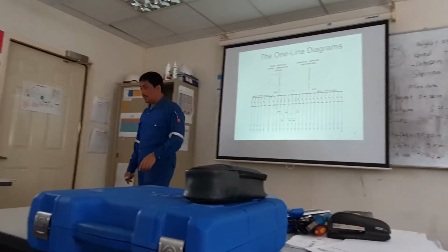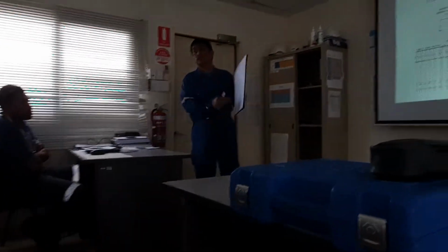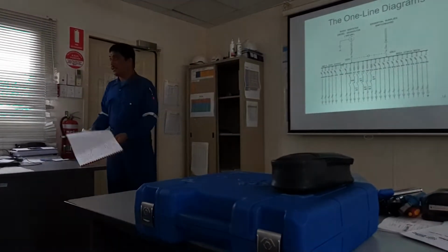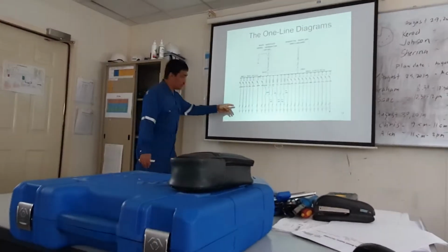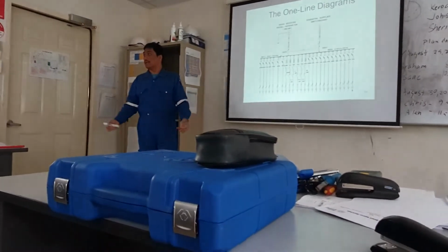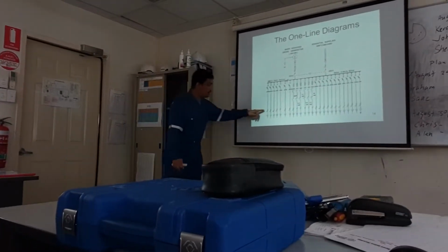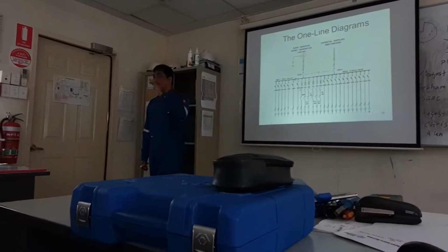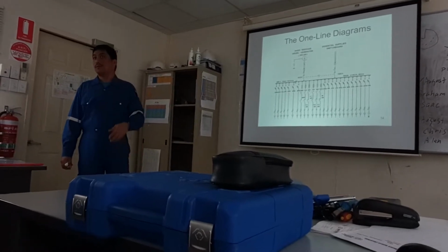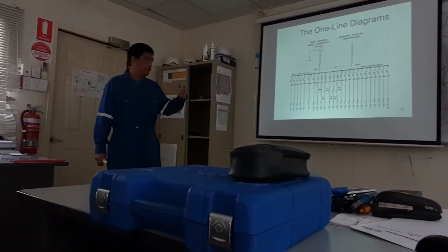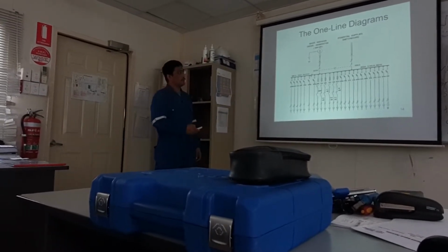If you are going to check some of the Exxon drawing, you will find symbols at the bottom. And it is clearly defined what are those wires. Okay? That wire could be also a grounded cable. I mean, buried underground. For me, I cannot decide. You know why? Because it is not on the legend. So once the legend is provided, it will explain if that is a cable, XLPE cable, underground cable, or what kind of cable is that. Any question?